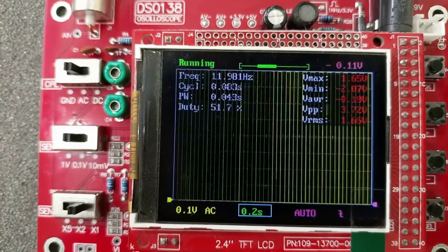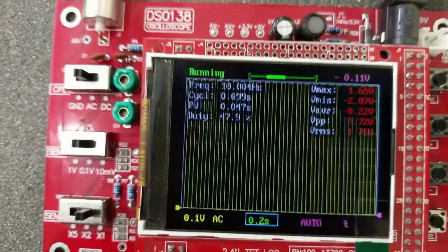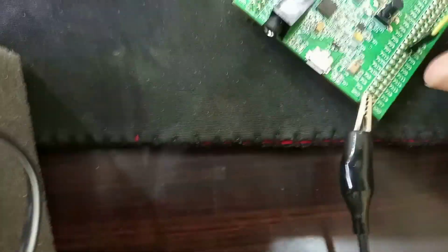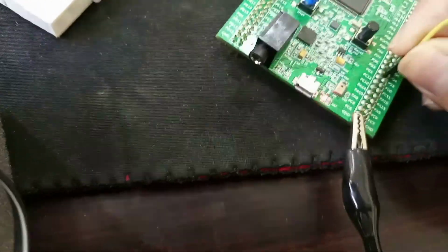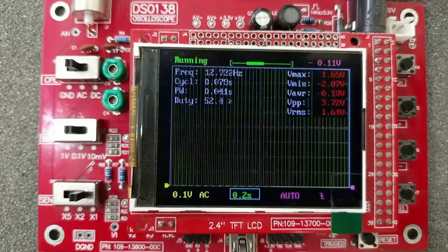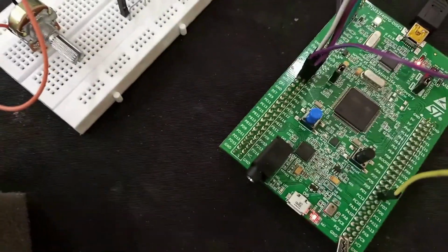This pattern is according to how much reactive power should be injected into the grid, and now I can also change it to PD4, which is again another output. Now you can see the switching signals. This switching signal should go to the inverter, where the inverter will change the reactive power output from the capacitor injected into the grid.